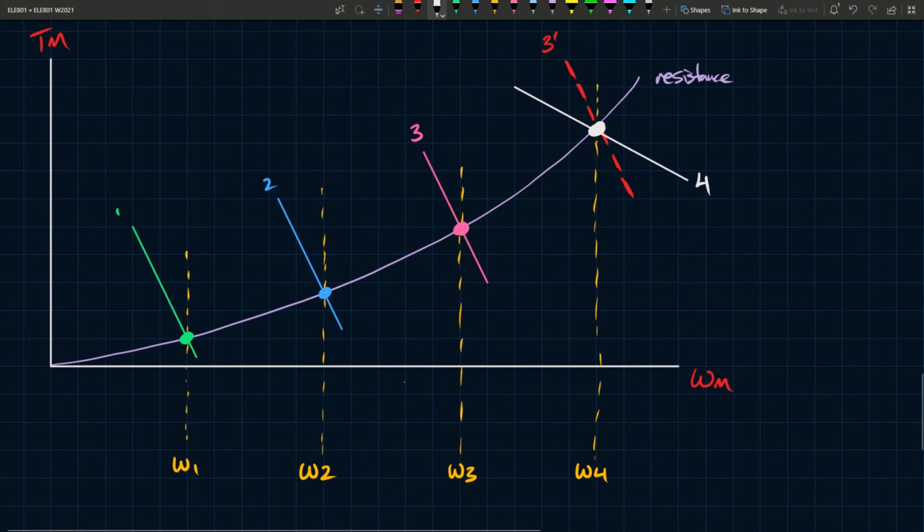So these conditions here, omega 1, 2, and 3, we can label, let's use this color here, and call these all full flux and armature voltage below the maximum, right? So let's say that's 1, 2, and 3. So let's say this region here, from here to here.